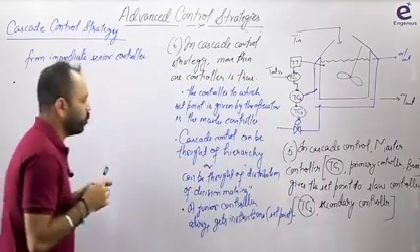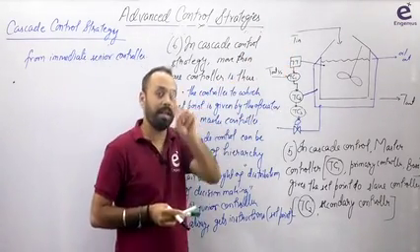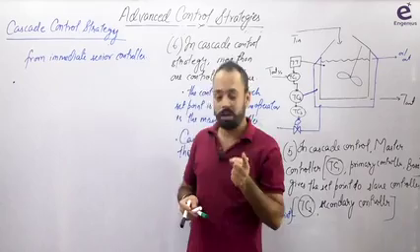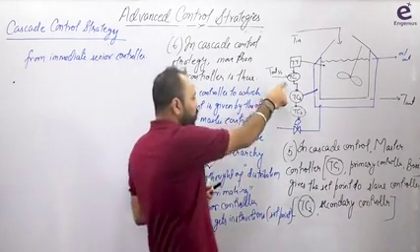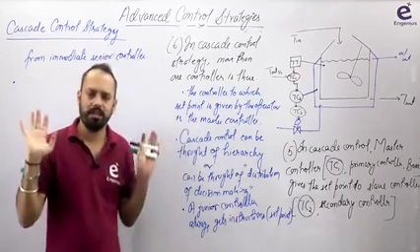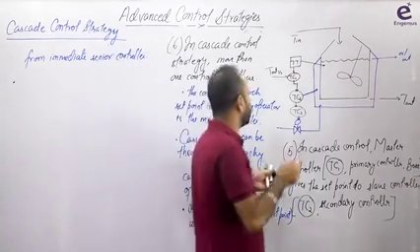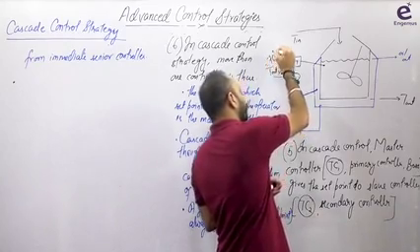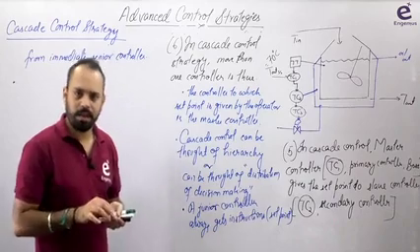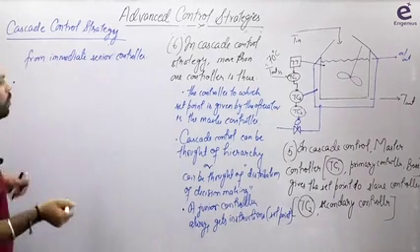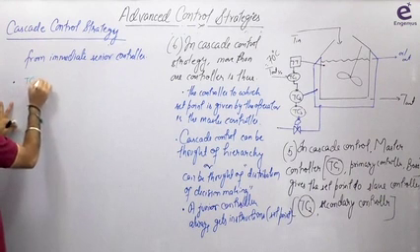Okay, see what is going to happen. This TC1, this is cascading, right? In a single controller, TC1 was in feedback control, TC1 was taking all the decisions. Okay, here what is TC1 doing? Look, TC1 is sitting in the chair, he is the boss, he is making only one decision: for maintaining, suppose T out SS is equal to 70 degrees Celsius, what should be the jacket temperature? That's it. Okay, with respect to this diagram I'm writing here, TC1 takes a decision.